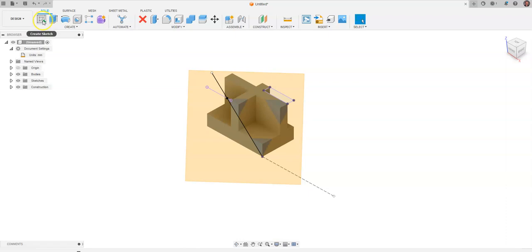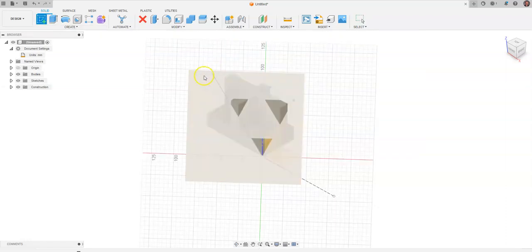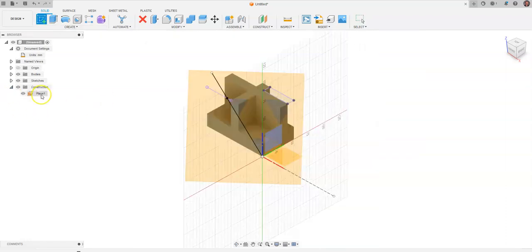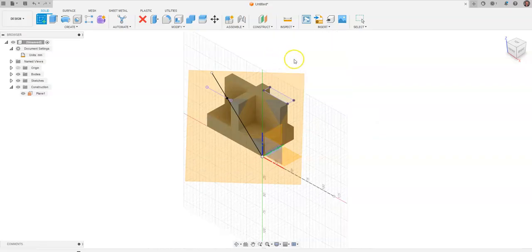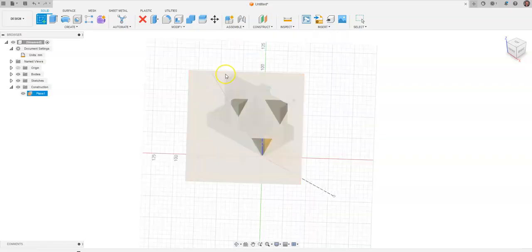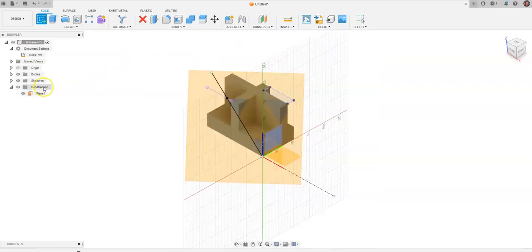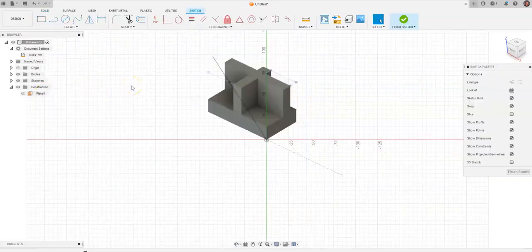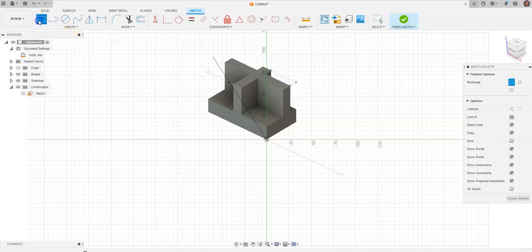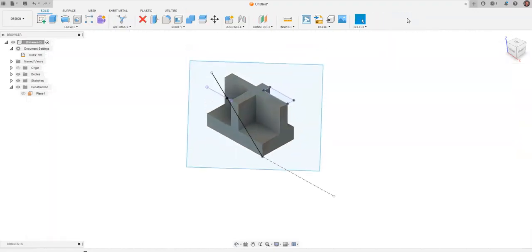We're going to grab Create Sketch and click on our plane. One thing we can do for this is come over and click on Plane 1 in this menu, and it's automatically going to select it. If you struggle sometimes out here, see how it's seeing different planes and doesn't know where to go, go over to our menu, go to Plane 1 and click, and automatically we get a straight-on, perpendicular view of that plane. I'm going to grab 2-Point Rectangle in this case, sketch a rectangle over the whole thing, and hit Finish Sketch.